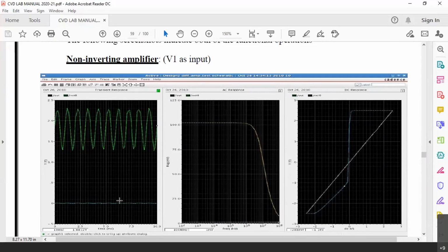That is a very minute wave. Let us say we give 1 millivolt here. We have a large gain here because of 2 N MOSFETs now. A differential amplifier will have larger gain when compared to the previous amplifiers we discussed. So you can see, we give 1 millivolt input. You can see in the AC response it is 100. It is slightly more than 100 also.